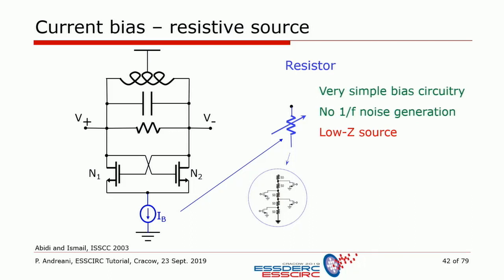An ideal current source has an infinite output impedance. But the resistances here, if it is 100 ohm, it's already a lot, okay? Unless you want to waste a lot of voltage dropping across this resistance. So they're small, and this impedance here is not very large. And the problem then is that there is a significant conversion, especially of 1/f noise from the cross-coupled pair into phase noise, which can be really troublesome.